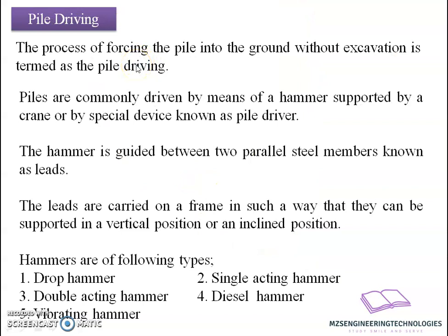Now let us go towards the activity known as pile driving. Pile boring is a boring activity. We are familiar with that. Simply we drill a hole up to a required depth and then we fill it. But in case of the pile driving mechanism, there are certain things we have to follow, such that during the installation the pile should not break, there should not be harm to the soil, or changes in the nature of the soil. So simply, pile driving may be defined as the process of forcing the pile into the ground without excavation.